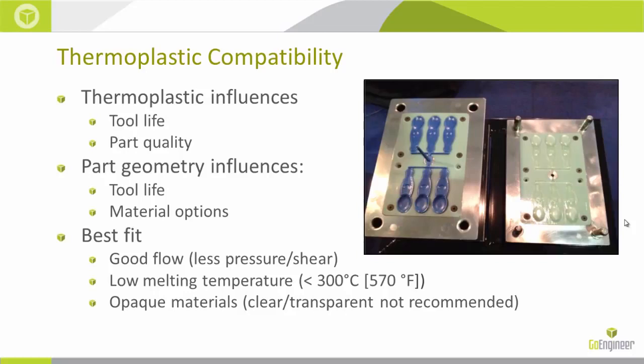So the best fit would be a material that flows well, meaning it requires less pressure, a low melting temperature, less than 570 F, and really opaque materials. So clear and transparent thermoplastics, we haven't really seen a lot of success with those yet.